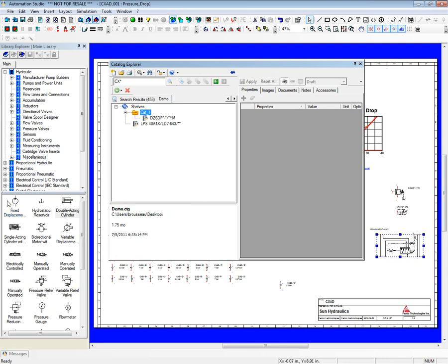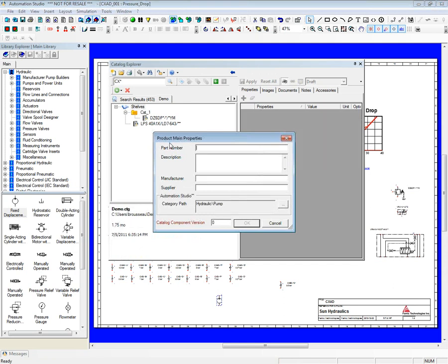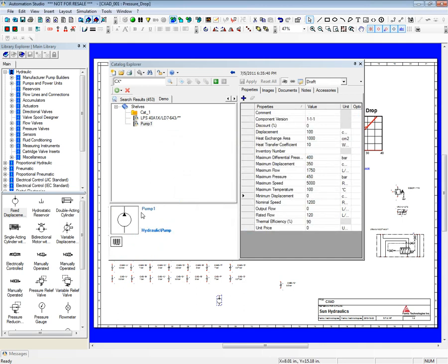And if you take generic components from the library, for example, I took this pump, you can customize it and then put it in your catalog again. So you won't have to do the same job again of modeling it. So you'll give it a name, because here it doesn't have a name yet. Call it pump 1, let's say. So now we also have pump 1.